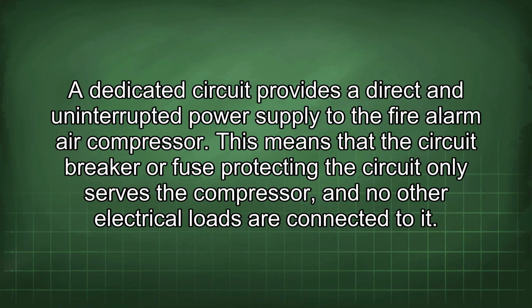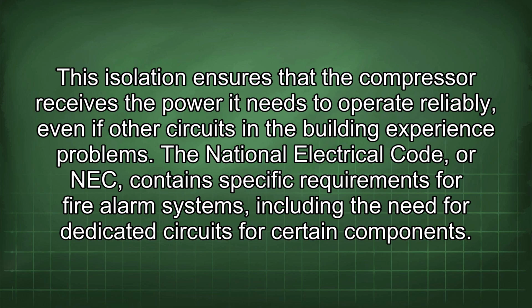A dedicated circuit provides a direct and uninterrupted power supply to the fire alarm air compressor. This means that the circuit breaker or fuse protecting the circuit only serves the compressor, and no other electrical loads are connected to it. This isolation ensures that the compressor receives the power it needs to operate reliably, even if other circuits in the building experience problems.